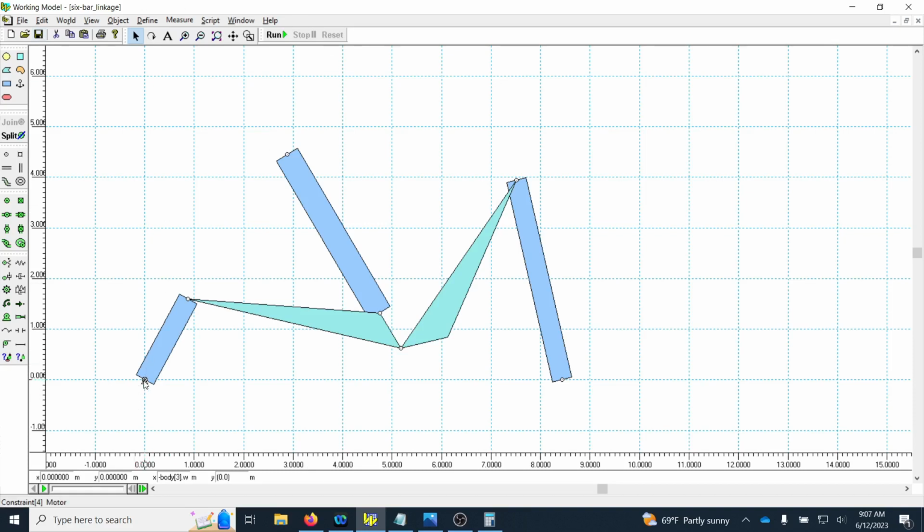So I have the motor here, and I have all the links connected. We tested that it works. Now something else I want to do is, let's say I want to find the positions or the profile of the motions of 2 points along these 2 links. So I can click on this point element and put a point anywhere on either of these links or even the blue links as I wish. So let me put a link point right here.